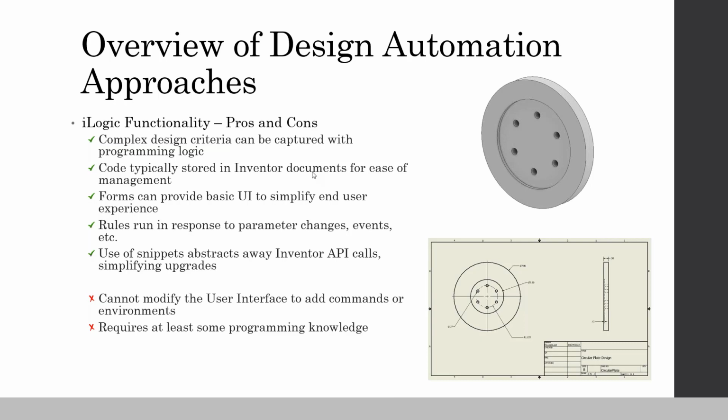And because you've got that complex logic, you can react to and validate the inputs. If you're not using iLogic and you're just using parameter inputs, it's very easy for someone to provide an invalid input that breaks the model. With iLogic, you can get complex if you need to make sure that when a number gets put in, if that number isn't right, we can either inform the user or modify it to something that will be okay.